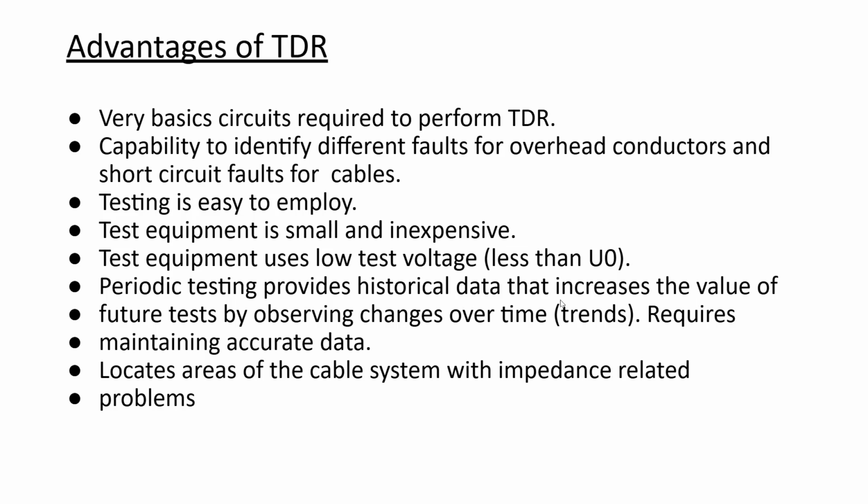Periodic testing provides historical data that increases the value of future tests by observing changes over time. If we continuously employ it for monitoring the cable, we can have the already recorded historical data. We can use it as a signature and verify where the changes are. So from that data, we can easily identify upcoming problems, or if there is any problem in the cable. That is the beauty of periodic testing.